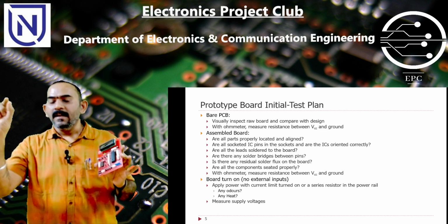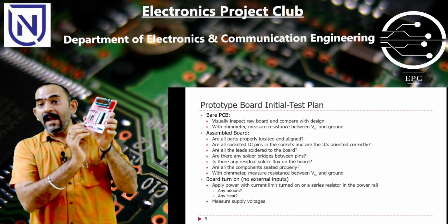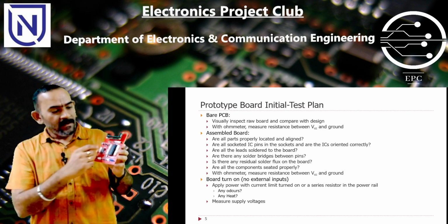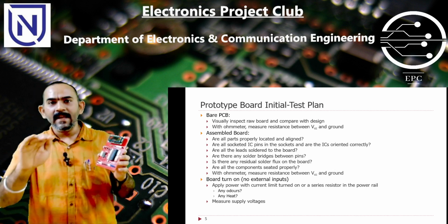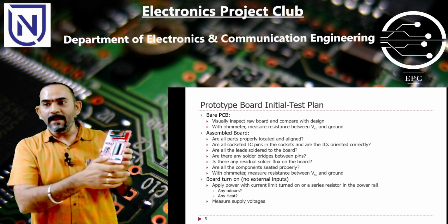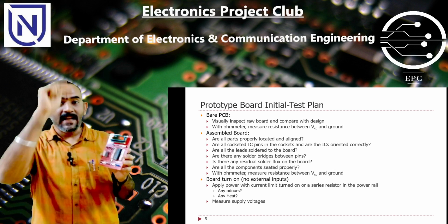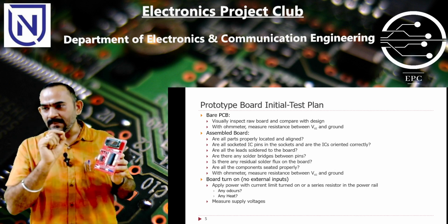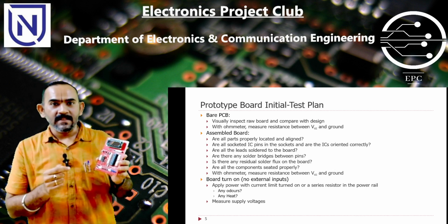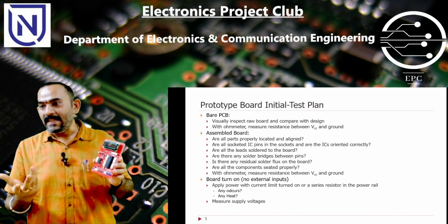The usual cause: you take power from these pins, the supply input, where you take a large amount of current, then individual components take current in moderate amounts. Now assume that instead of giving a plane for carrying this large current, you have just given small thin traces. Thin wires have higher resistance, and when more current flows through, the wire starts heating up.